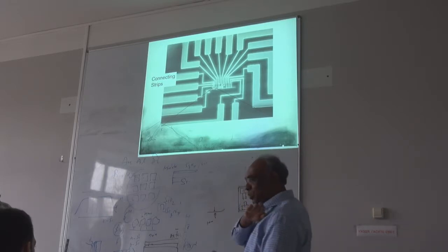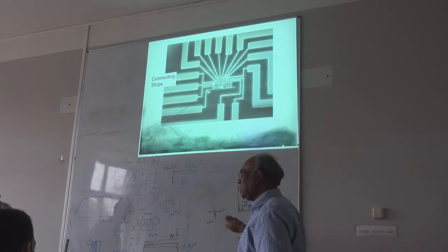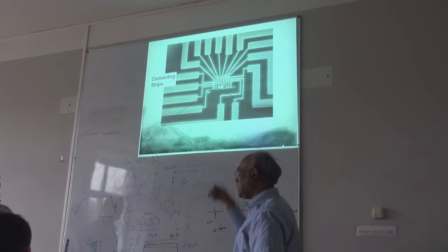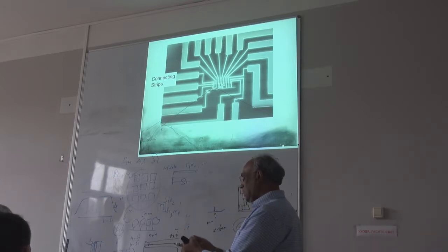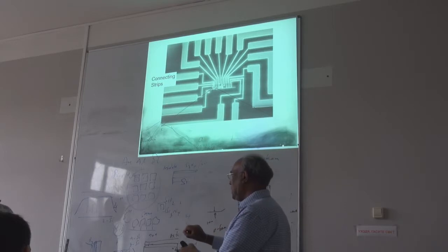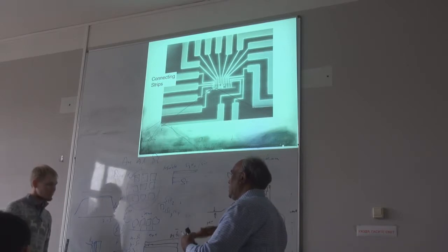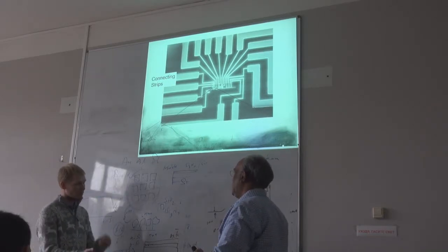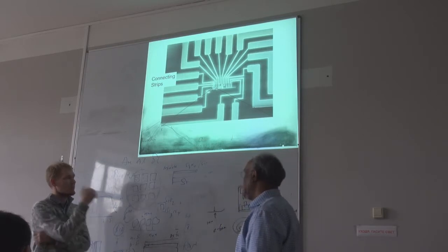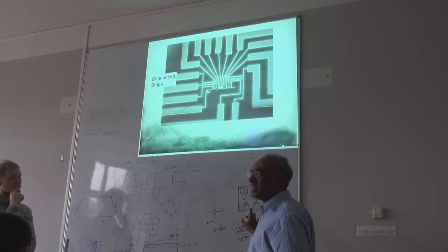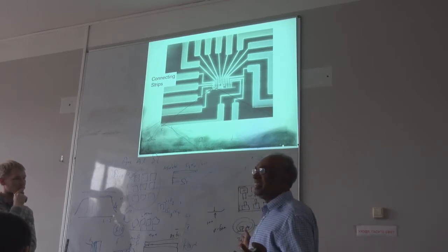So now we put the photoresist, then E-beam lithography is done using a scanning electron microscope. That's the electron source. You can raster your beam, and at the same time you can do the imaging, so you can view and write at the same time. When you put the photoresist, you cannot see the nanotubes, right?